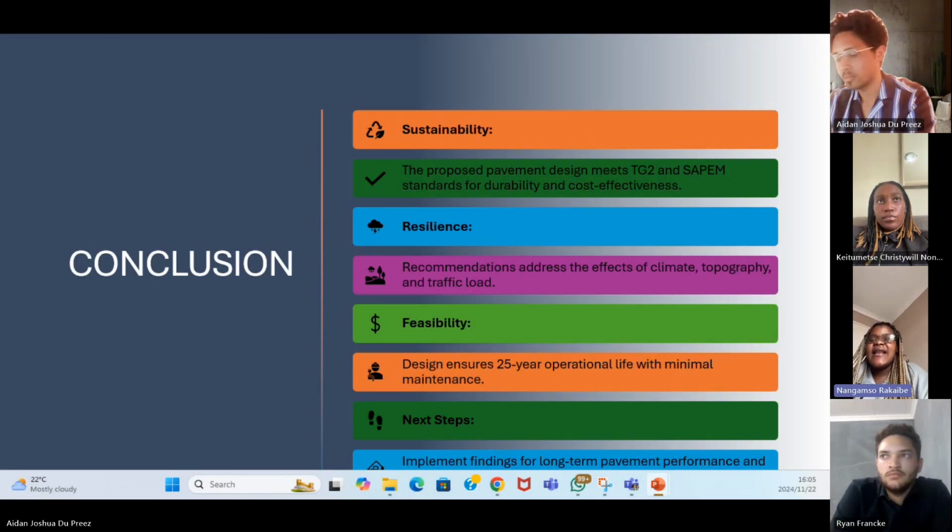Drainage design: the analysis highlighted the importance of both the subsurface and the surface drainage solutions. With the region's coastal climate and seasonal change of rainfall, the implementation of proper camber, cross slopes, perforated pipes, and geotextiles is critical in preventing water infiltration into the pavement structure, thereby ensuring long-term stability and preventing moisture-related degradation.